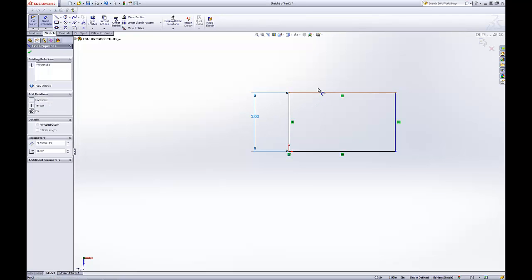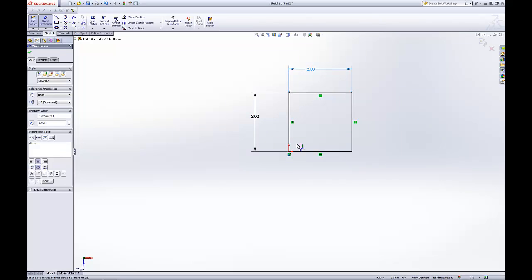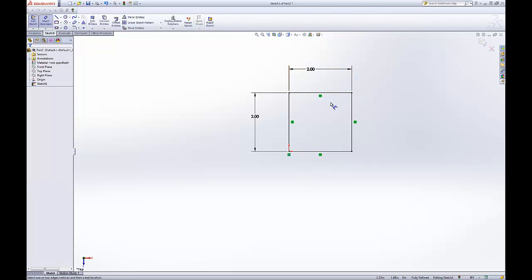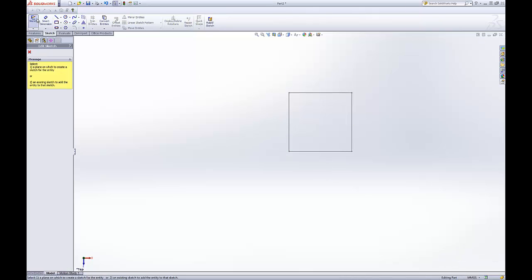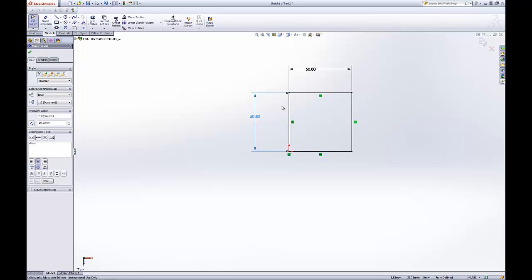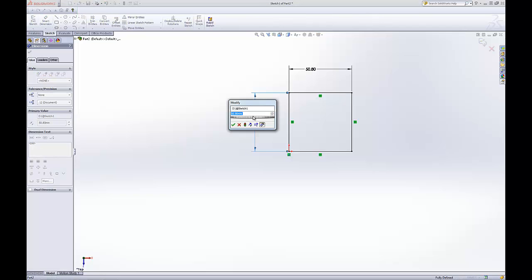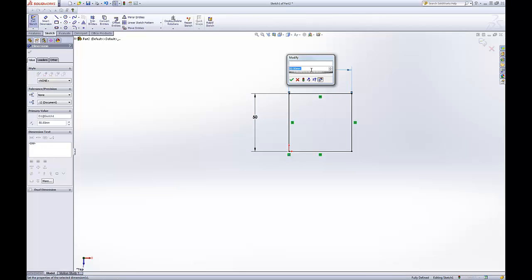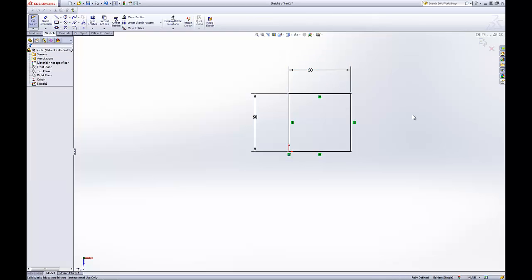to what we want. Now there's several ways to change if you're inches or metric system. You just come down here and click on what you want. It's going to push you out of the sketch, but then you can go right back into it. Just click on it. You can see now we're in centimeters. And you can change dimensions anytime by double clicking them. But you can see now everything's darked out and black and you can't move it.